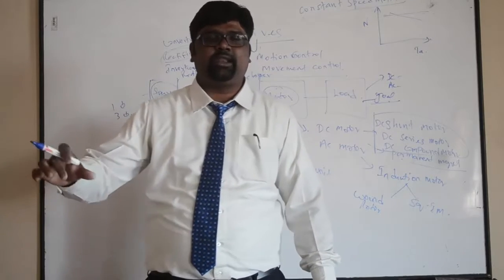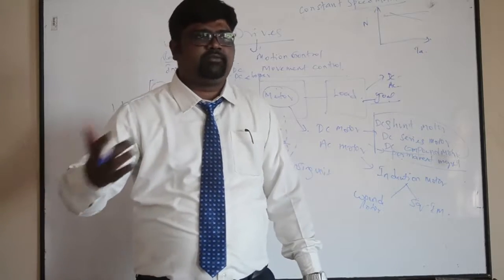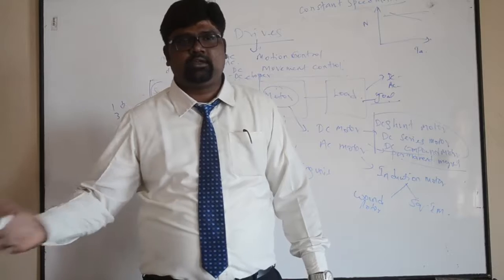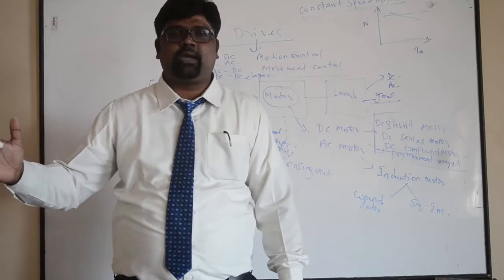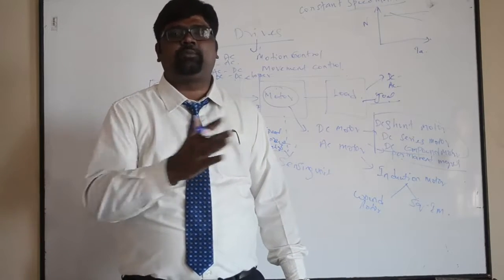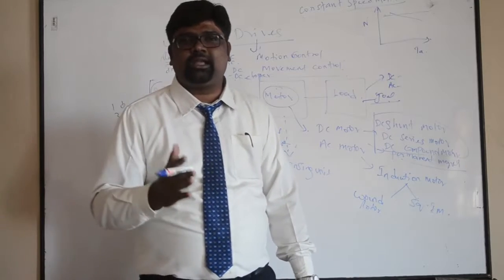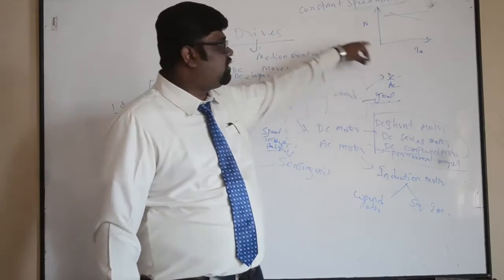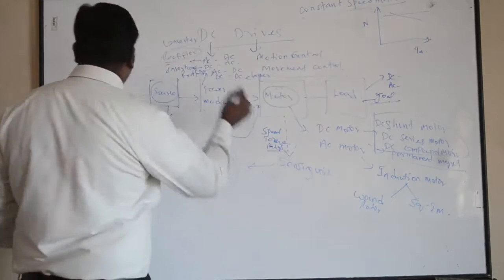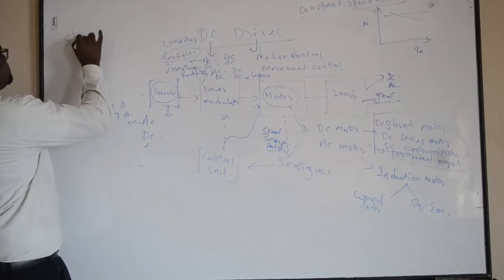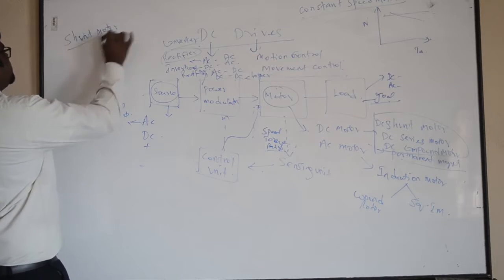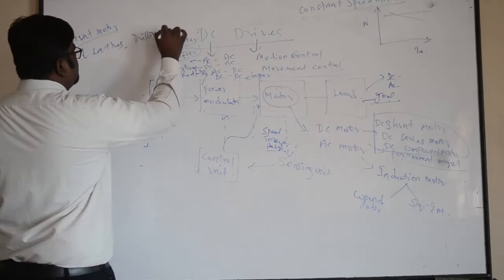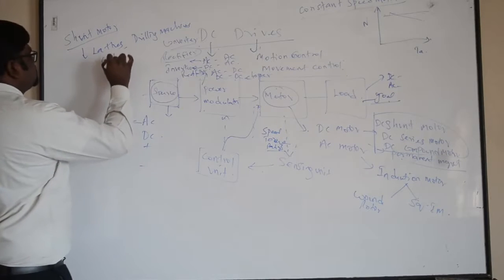The lathe machines will be running from the morning until afternoon or evening, so there is a huge time gap where it will be functioning for a long period of time. For that purpose we need a constant speed. So I am writing here shunt motor, a constant speed motor we can use in lathes, and even in drilling machines, cutting tools, etc.